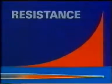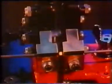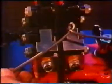As the electrical resistance of different metals varies considerably, they can be chosen to produce high resistance and heat where required. For instance, current flows easily through the aluminium or copper wires of a flex, but meets high resistance in the thin nickel-chrome element of the fire. High resistance also occurs at junctions. When two rods are pressed together and a current passed through them, the ends melt at the junction and weld under pressure. This is a resistance butt weld and one of 5 resistance welding processes in everyday use.